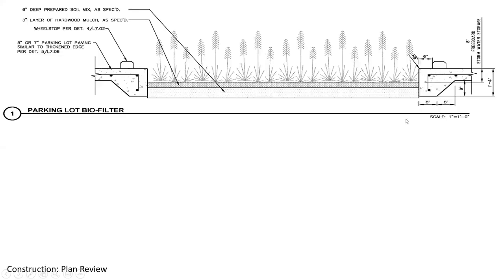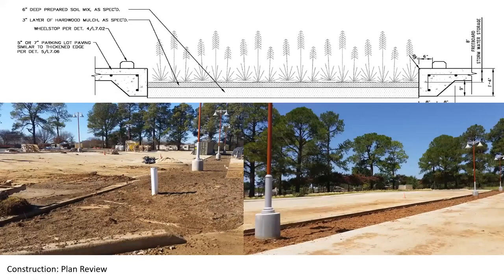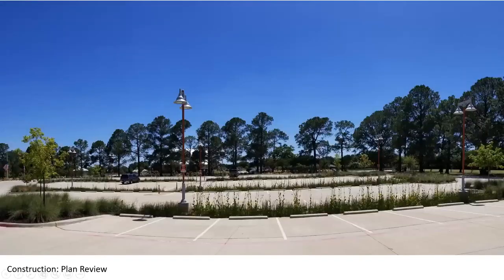So this is a really cool park project we did in North Texas. What's interesting about this was in the original design, they called for a 6-inch drop off the pavement. And when the contractor installed the landscape, they actually had the landscape go directly up against the pavement. So they had to come back in and cut it down. But they got some really cool results out of this. So you go out and look at this project, it's really great. All you see are these large bioswales that end up draining into a bioretention system on the low side. And what's really cool here is you really don't see any drainage inlets, right? All the water flows into this landscape, and then the landscape takes care of a lot of the infiltration and the drainage.